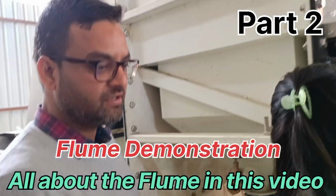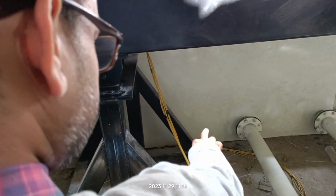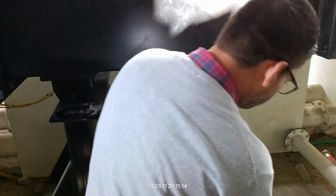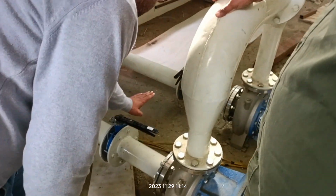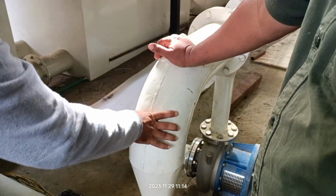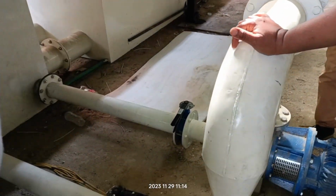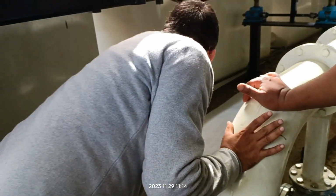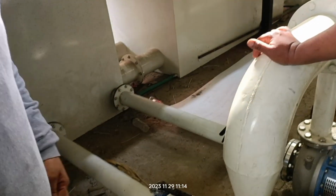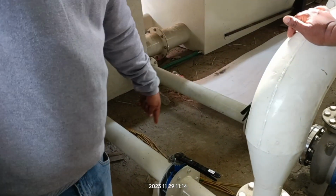These two pumps will take the water from this tank. Each pump has a separate control valve. If I want only this pump to be operated, I will switch off this valve. Otherwise, what will happen? It will take the water, half the water will go from this side, and the rest of the water will go back into the tank. So because of that, we require two valves.